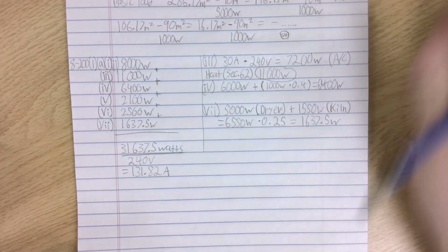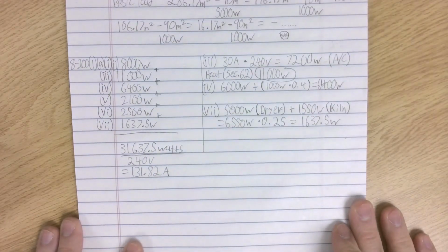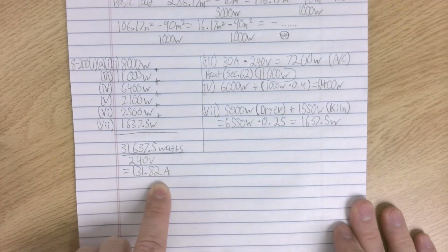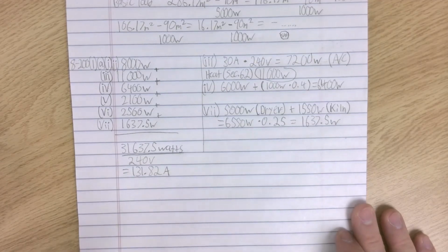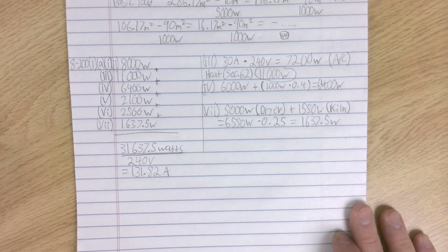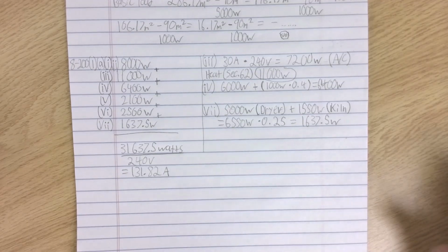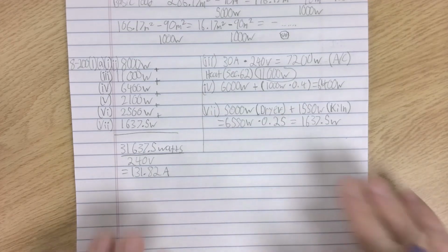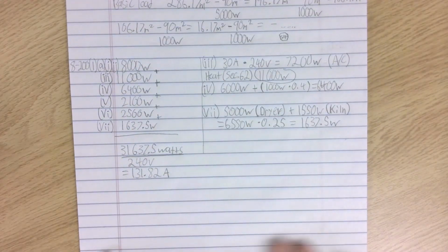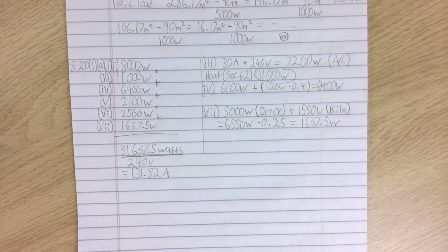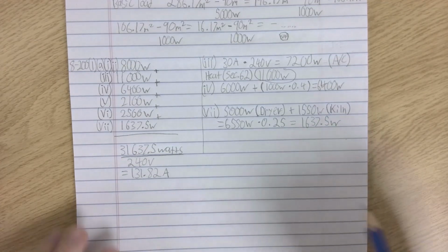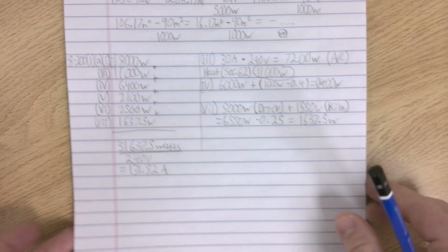So if you remember from our section 4 stuff, I don't believe it's in the question, but let's just say that we have 3 RW90 wires that are run in PVC underground. That should have been included in the question, but we're just going to say for our practices today, it's 3 conductors in PVC underground. Goes up to the meter, from the meter to the panel, etc. And so that ampacity is going to go on the conductors.